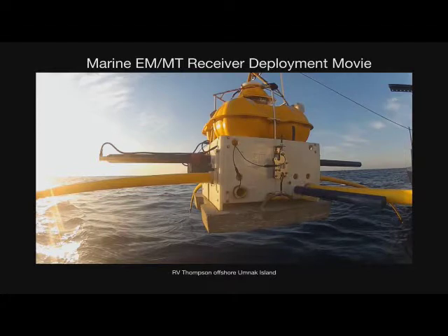We just use these tubes because they're stiff enough so they're not going to flop around too much on the seafloor. In order to make these measurements, the magnetometers are really sensitive to tilts and vibrations. So we had to design these big concrete slab anchors that are attached to the instrument frame, and that holds the instrument relatively stable on the seafloor. And then we have these flotation packages, which are used to float the instrument back up to the surface when the release mechanism, which is shown here, is triggered at the end of the experiment.